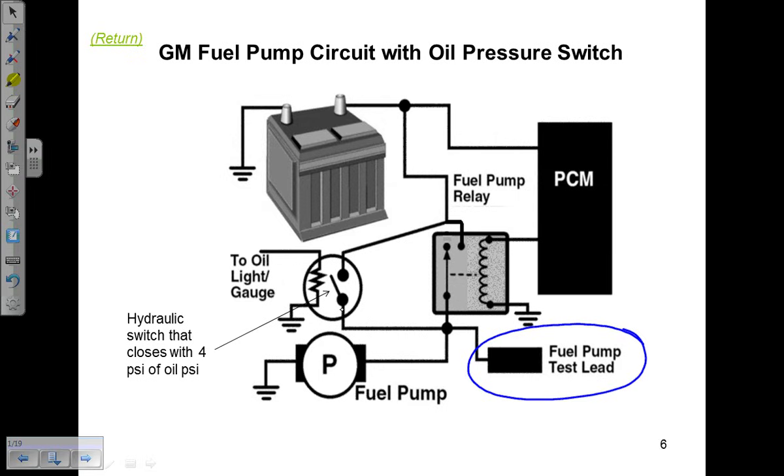Situation that you're going to run into a lot is the vehicle's going to come in and it has no fuel pressure. It's a no start. And before you ever put a fuel pump in a car, you would always want to check your power and check your ground in a loaded situation. And when I say loaded situation, that means that the circuit is active and alive, the relay's closed, you're sending 12 volts down to the pump, and so you check your feed, and then your ground, you want to see 300 millivolts or less, something like that. That would be a good ground.